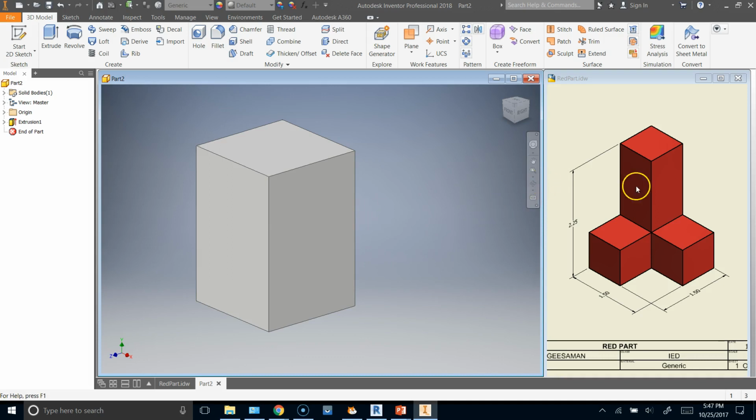Next step now is I am going to, on the front face of this, remove a rectangle because the front view of this shape is just an L shape. So I'm going to remove a 1 block wide by 2 block high rectangle. I'm going to do that by doing the following. I'm going to start a sketch on the front face.